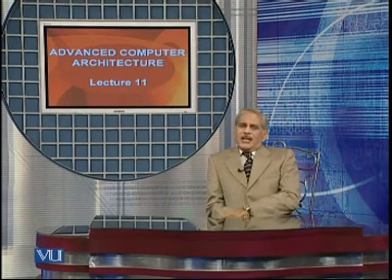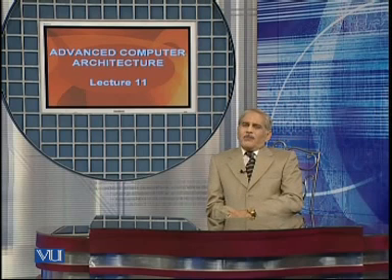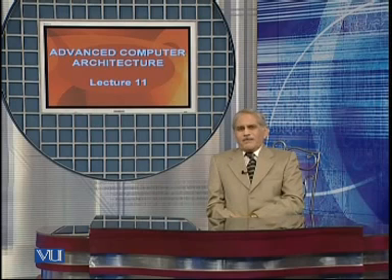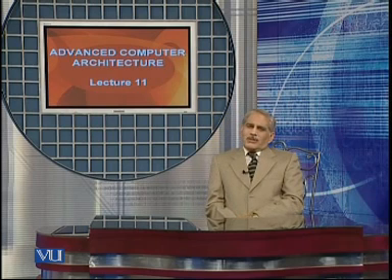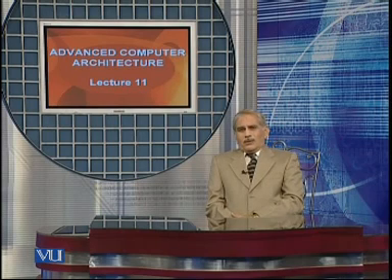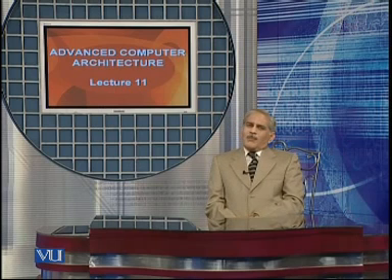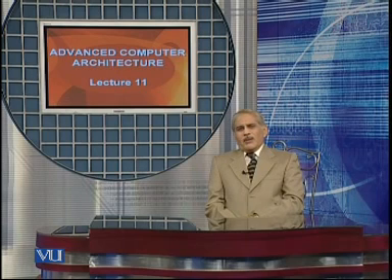The prediction technique is one where we make a guess in the beginning, and we can design our circuit based on the concept that the branch is always taken or the branch is not taken. This type of guess reduces the overall number of stalls required to eliminate these hazards.